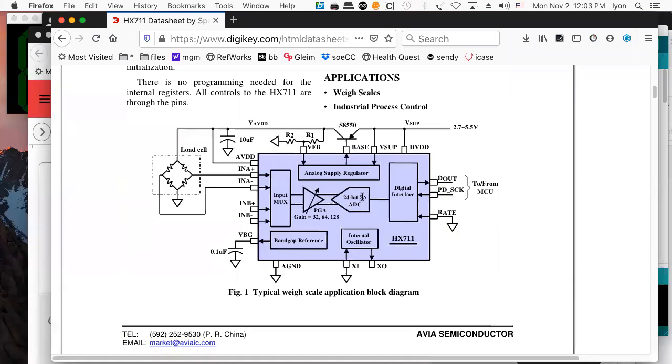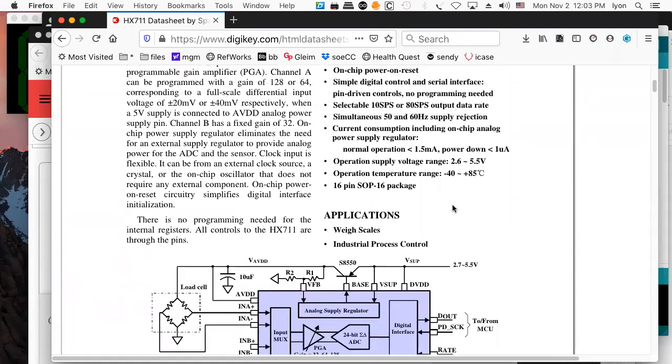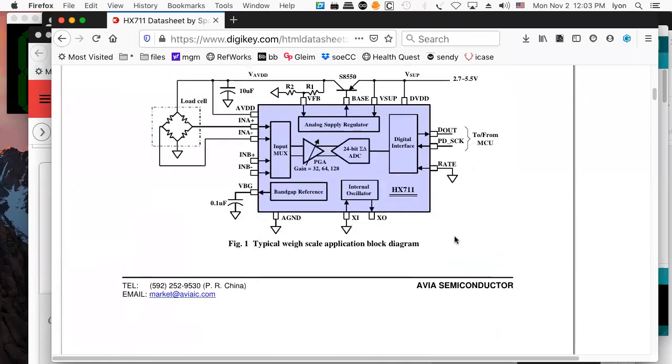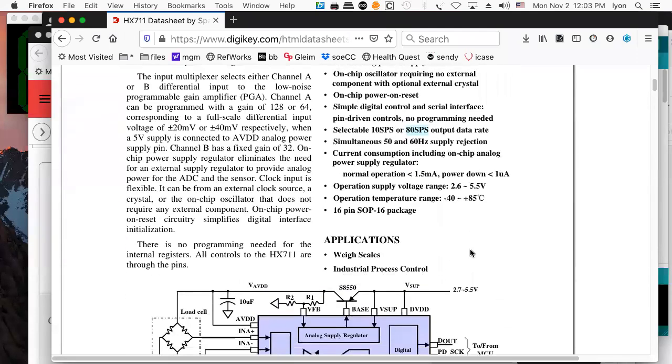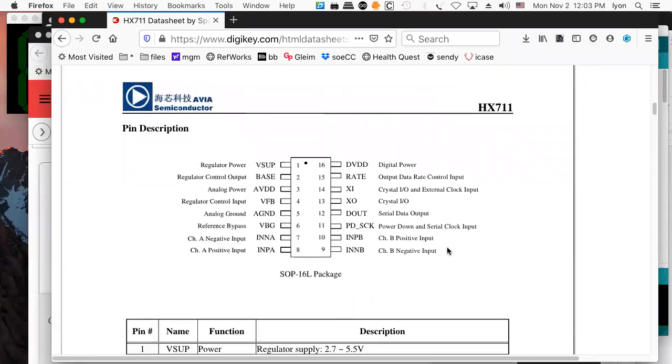And it essentially gives you the ability to sample relatively slow rates of change with very high precision. So this is a great kind of ADC converter to use if you don't plan on sampling very often. And the sample rate on something like this, he's saying, is like 10 samples per second, 80 samples per second. Or if you know that you're going that slow, it's relatively easy to build a high precision ADC converter. And that's perfect for doing something that you're just measuring the weight on.